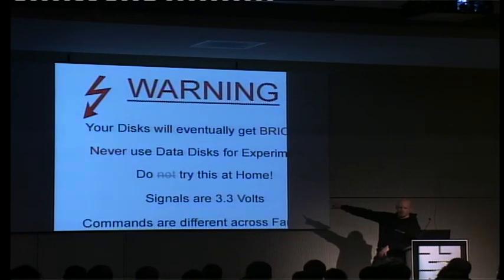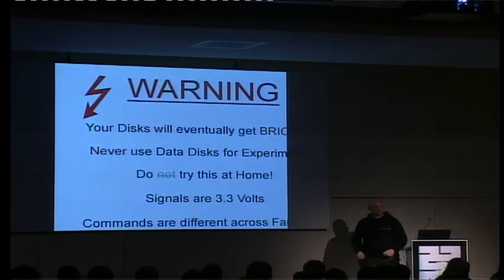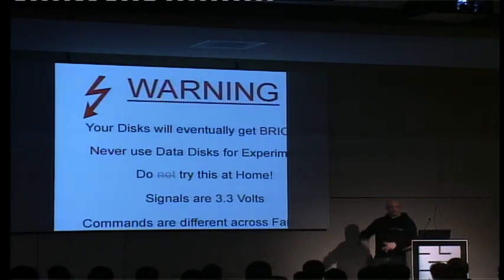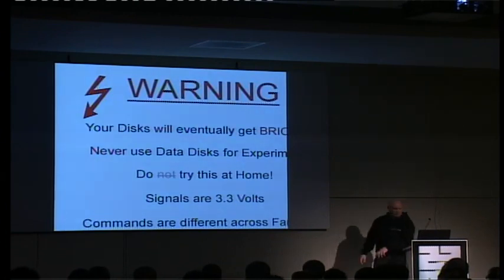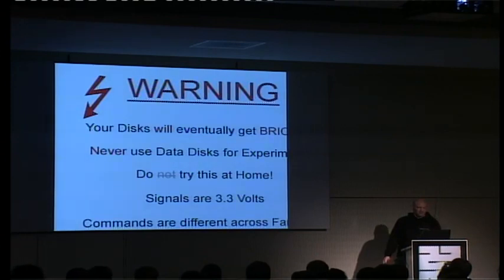Do try this at home, because that's the reason why I'm doing this presentation, to get more people into hard drive reverse engineering and playing. And yeah, the signals are 3.3 volts, and I have to read that for you as well. Commands are different across families, meaning I will give you now a little list of commands that you can talk to the hard drive, but they are only working for the Seagate 7200.10 hard drives.